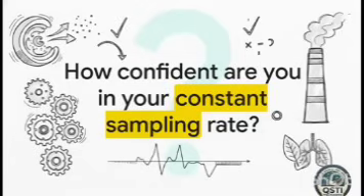As we wrap up this explainer, I really want to leave you with a crucial thought. EPA Method 201A is basically a marvel of applied physics. It uses mechanical cyclones to perfectly separate invisible particles suspended in scorching, turbulent industrial exhaust. And the whole thing hinges on that one absolute golden rule, maintaining a constant sampling rate.